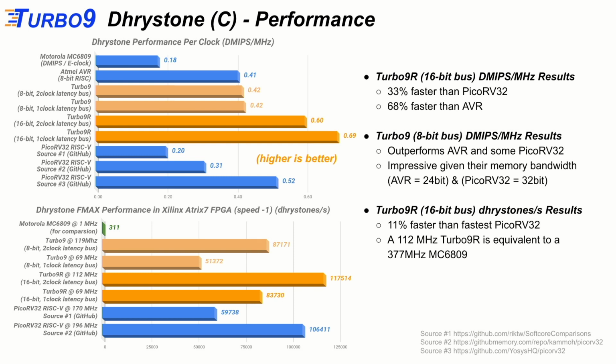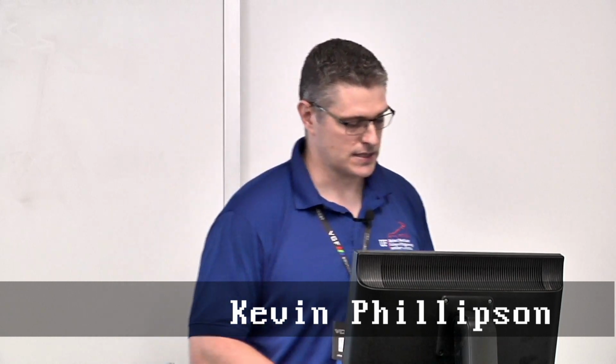And then we have the Fmax performance. What that is, given a specific FPGA or a 7-nanometer processor or whatever, how fast can your design run? That means how well designed is the microarchitecture to limit your worst case propagation path, so you can basically run it at a certain frequency.